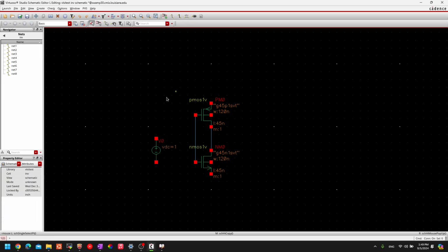Let me do this again. So I pressed on C, hit C, and then click this DC source. Move it here. Click again to place it. That's about it. Now you got 2 DC sources, right?